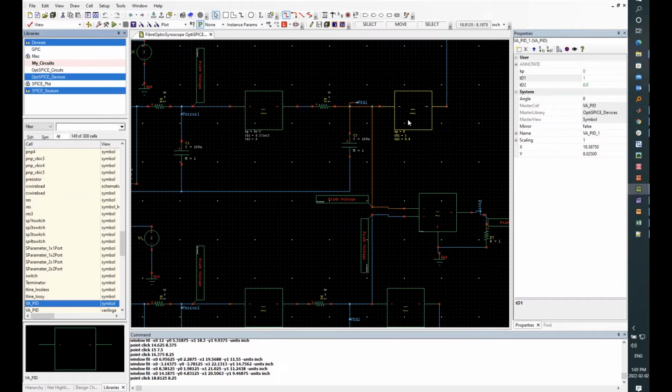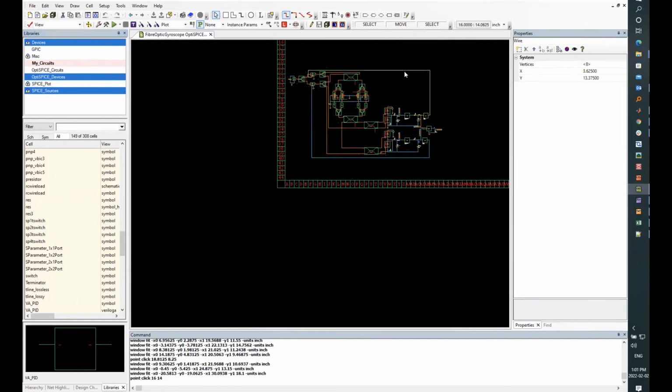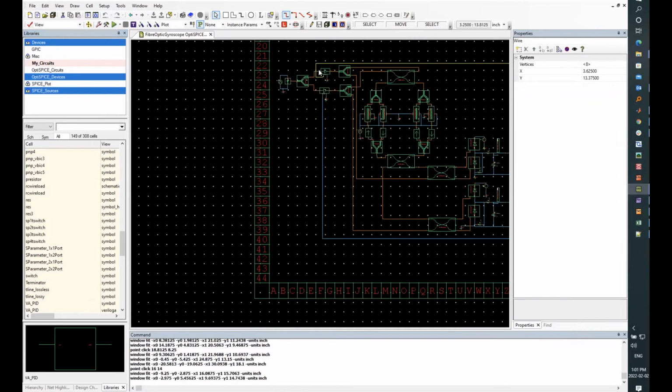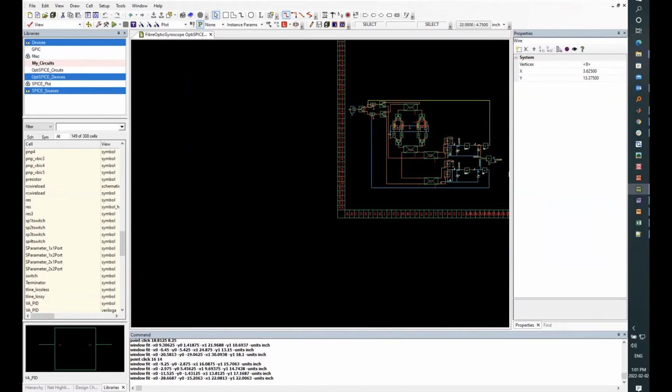This integrator following the PID controller generates the phase modulated signal that shifts the carrier frequency going back into the resonator. So this signal, if you see this wire, basically feeds back into the resonator here. So this feedback loop is essential for the carrier frequency to track the resonance of the ring resonators, and then finally at the end here.